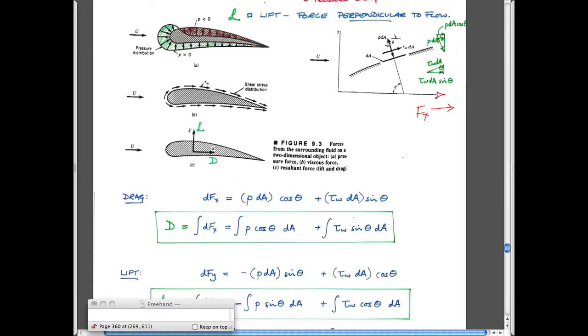So you have a pressure that's applied here. You're interested in the component which is in this direction, it'd be this one, right? This would be it here. So this is the pressure applied on the face of this here. It's over some area which is just some length dA. So the total force is going to be this pressure times the area. And if you want to correct it for the component that's pointing in this direction, it's just going to be P dA times cosine theta, which is this term here, right?